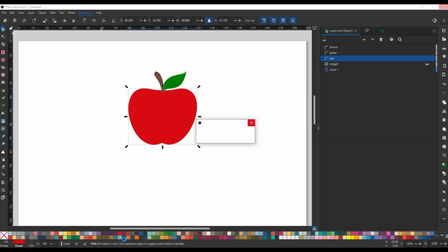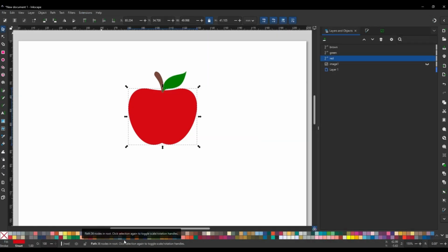This brings us back here to the image. It is very important that these settings do not apply to the whole image, but to the selected element. So for every single element, you have to go into params to set the values, so the machine knows what and how you want to embroider. These are what will make up for the final embroidery file, which you will load into your machine in the compatible format. We've done the apple, so let's look at the leaf.